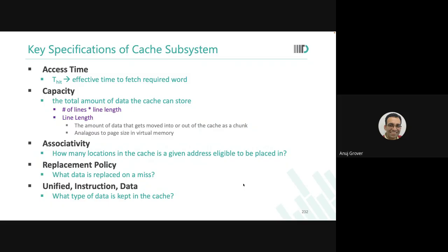The replacement policies work with set associativity also. For example, you have 4 sets. Anyways, when you bring data from the main memory, you have an option of choosing any of the 4 sets. Which one would you use? That is what the replacement policy means. Which one would you replace? Are you getting it? So replacement policy is another very key parameter which defines a cache subsystem.